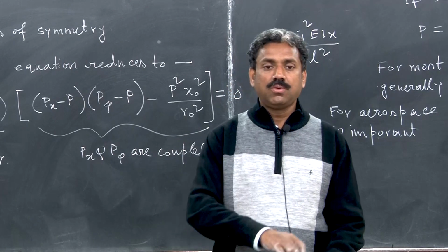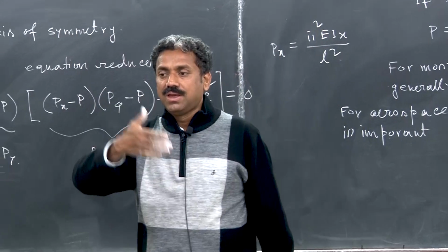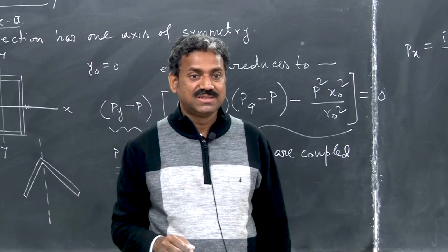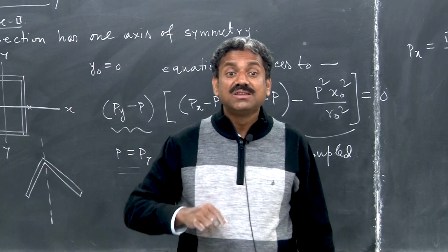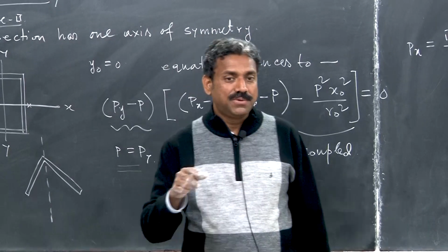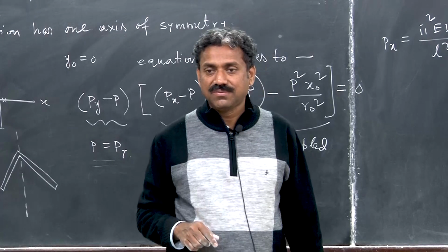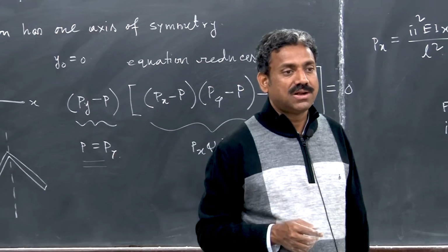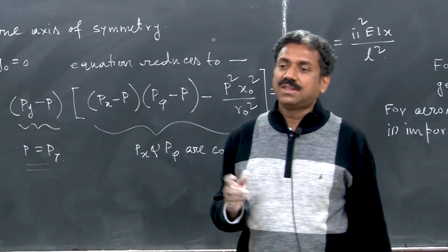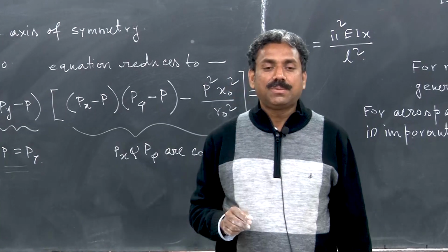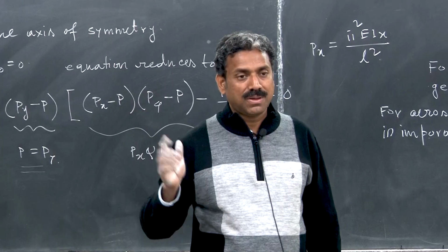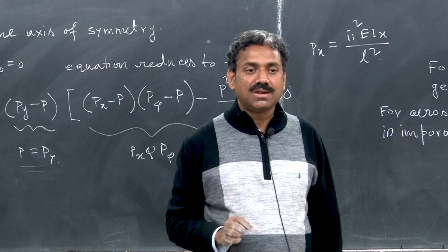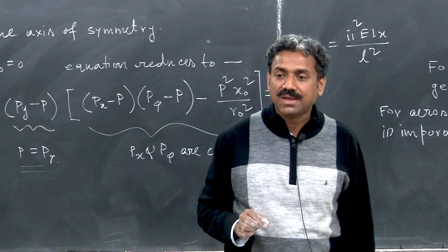If only a single angle section is connected at one side of the gusset plate, then you have to check for torsional flexural buckling, and there are some formulas given in the Indian standard code. Unfortunately, that formula is adopted from a conference paper published by some IIT Madras fellow, and this is not even validated or verified through experiments done in a lab.